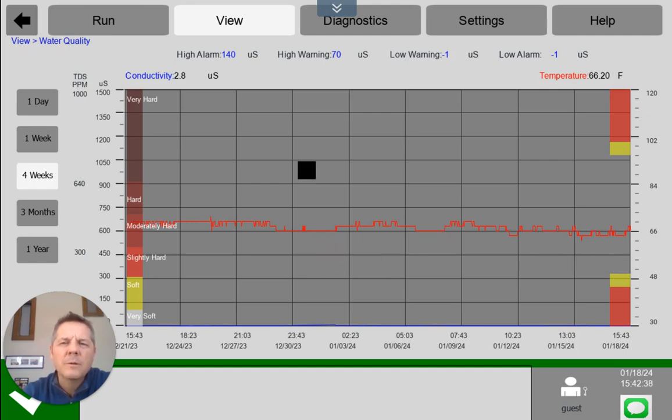But probably more importantly for the coolant that you're using, it was probably designed for a certain hardness of water. So we've got some sensors on our system that are continuously looking at the water as it's being used for each fill-up event in the machine. In this example, the customer is using very, very soft, very well-conditioned water, and it doesn't really have much hardness in it at all. So that blue line is on the very, very bottom of this graph here.